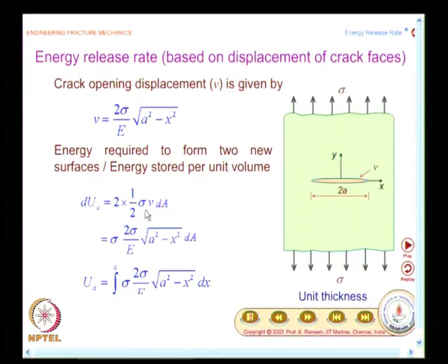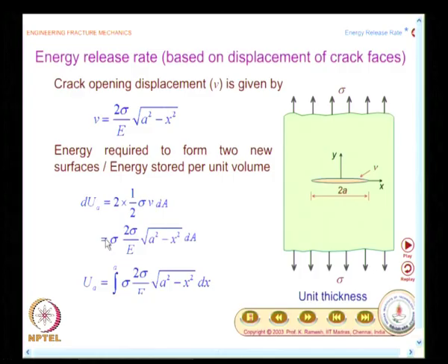And we have looked at a thought experiment to justify that the force acting on the crack faces is sigma. This is the conceptual step. We have got the crack opening displacement. When I have to find out the energy, I need to find out what is the force and displacement, and it is quite subtle. To reconvince yourself that you have to apply sigma to open the face is very subtle. If you catch that, then you can write the expression for energy, then it is only an exercise in mathematics.